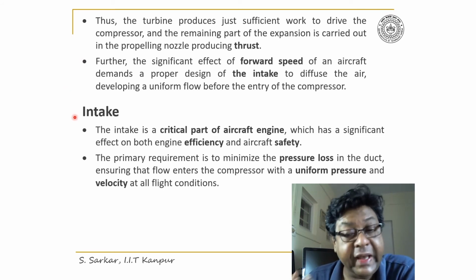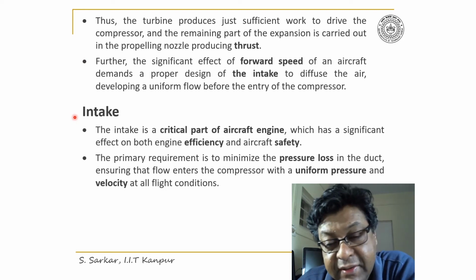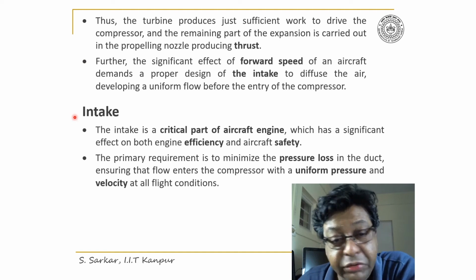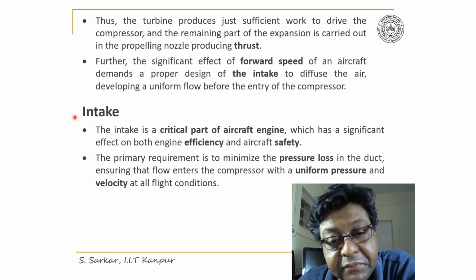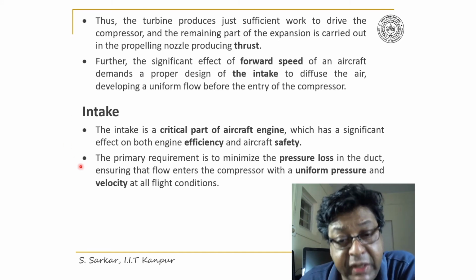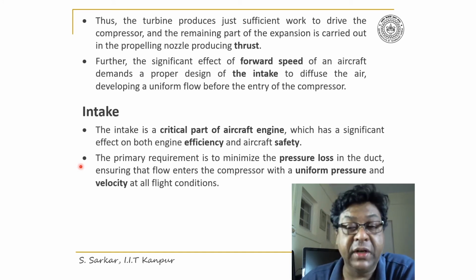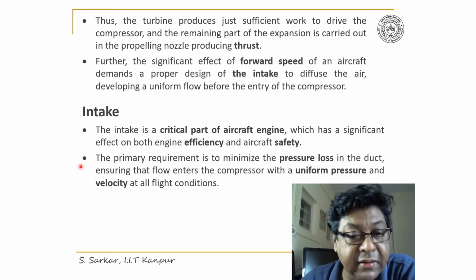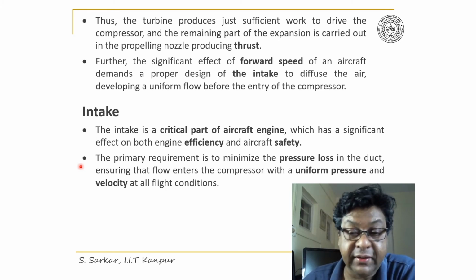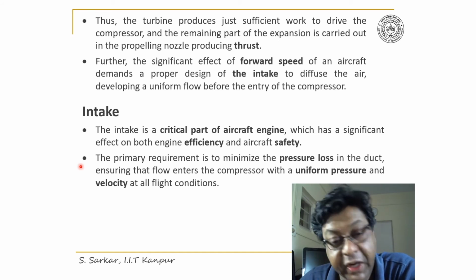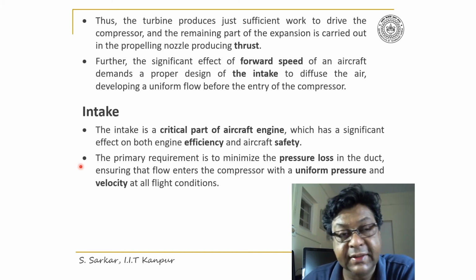The intake design is very critical for the aircraft with respect to its efficiency and safety. The primary requirement of the intake design is to minimize the pressure loss in the duct, ensuring that the flow enters the compressor with uniform pressure and velocity at all flight conditions.